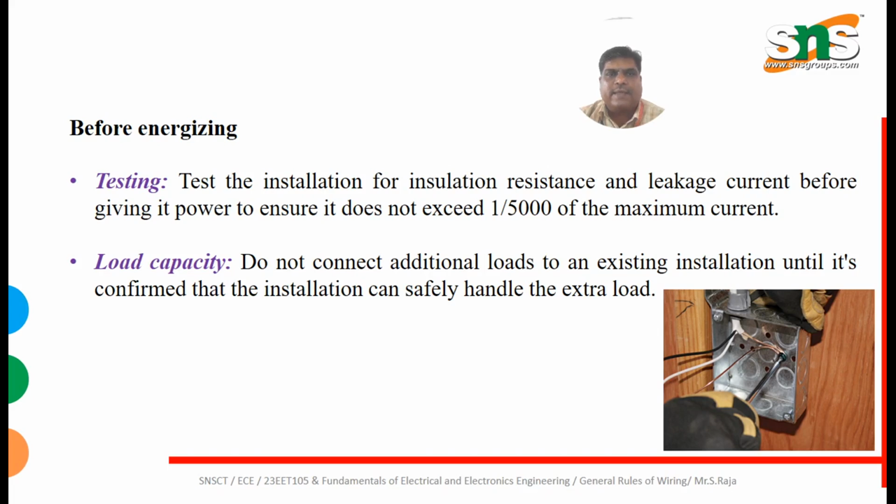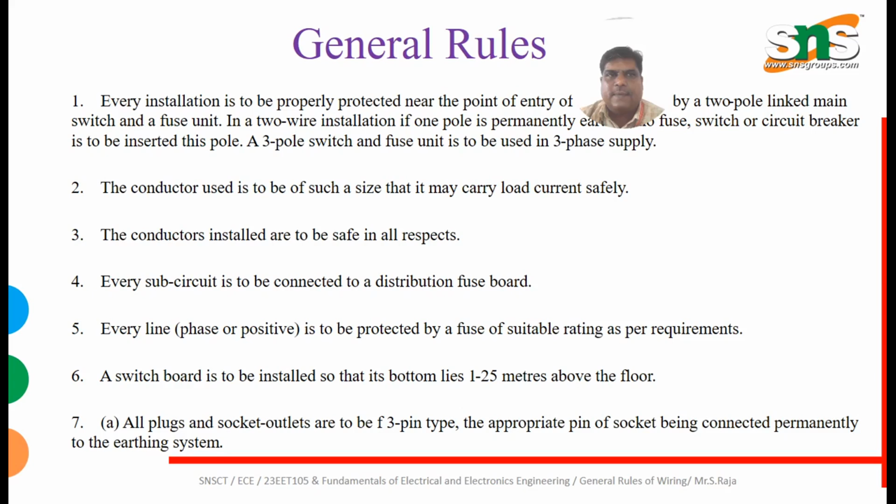Before energizing, we can go for testing. Test the installation for insulation resistance and leakage current before giving it power, to ensure it doesn't exceed 1/5000 times the maximum current. Load capacity: don't connect additional loads to an existing installation until it is confirmed that the installation can safely handle the extra load. So these are the general rules that we can follow in any working place.